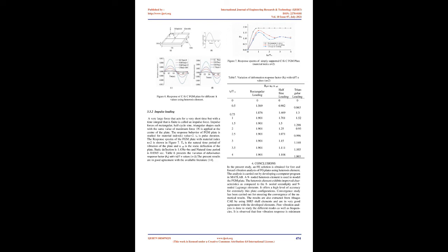3.3.2 Impulse loading. A very large force that acts for a very short time but with a time integral that is finite is called an impulse force. Impulse forces of rectangular, half-cycle sine, and triangular shapes, each with the same value of maximum force 1 N, are applied at the center of the plate. The response behavior of the FGM plate is studied for material index n equals 2.